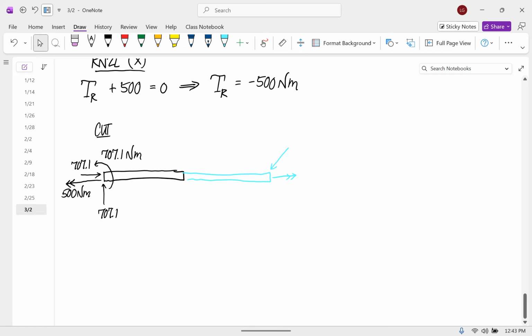And now, for the internal loads, we have to consider the loads that are applied to the black piece by the piece of the beam that we're not considering. That's a fixed joint, so we know it's going to be a whole set of force vectors and couple vectors. And I'm going to write them like this. I'm going to use the sign convention we used in statics.